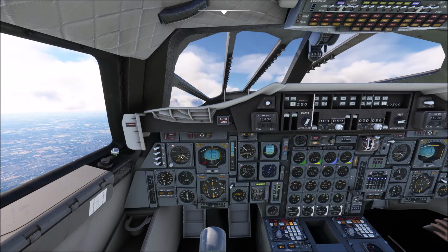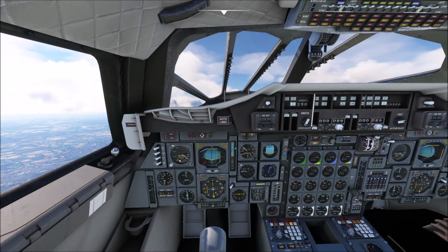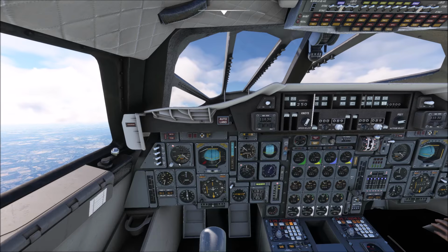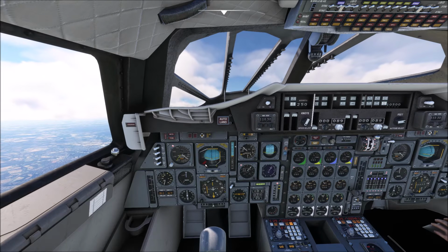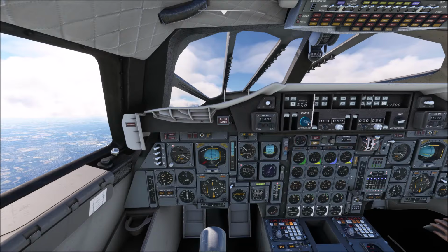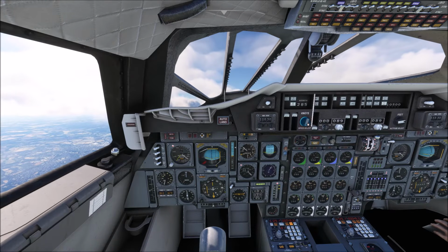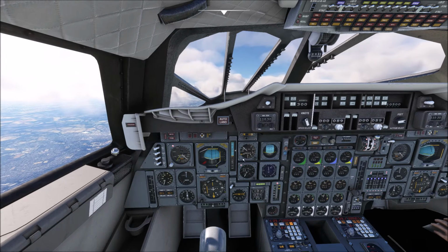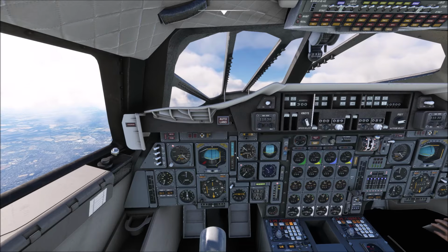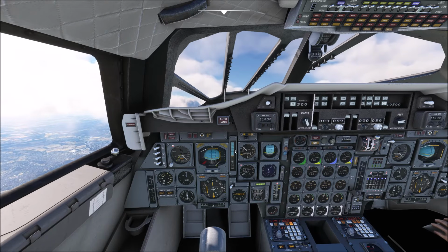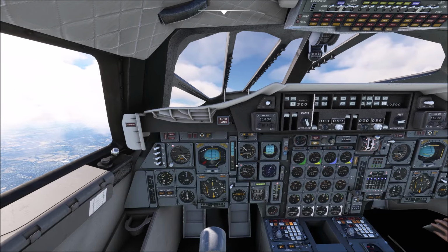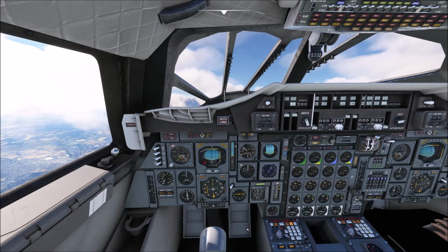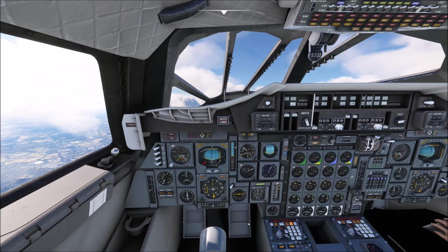You can see here this barber pole and the airspeed indicator is just above 400. That's our maximum velocity below 10,000 feet and below a certain Mach number as well. So we're just going to push that up a bit now to 300. Concorde will automatically lower the nose to allow the engines to pick up the airspeed and then reassess before raising again. And this is all a combination of the standard flight sim autopilot and custom coding to more mimic what Concorde would do because it's so unique.